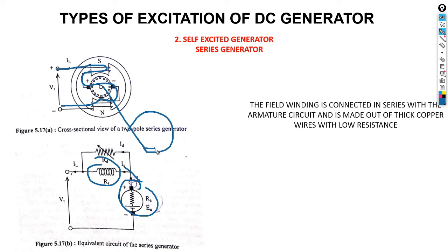Okay, but with this series circuit, there is no way to start it without any load, which means at the beginning already you need to have a load so that there will be a flow of current, because without a load there won't be any circulation of current. Can you see that? So once you have connected a load, you see that now the current can flow. Without a load there won't be any flow of current. If there is no flow of current, there won't be any flux that will be generated or an induced EMF.